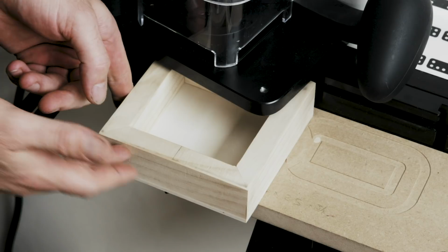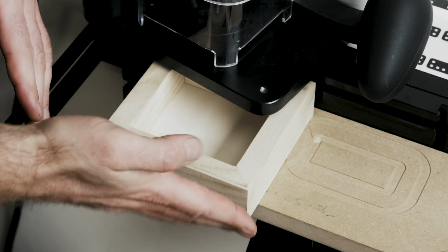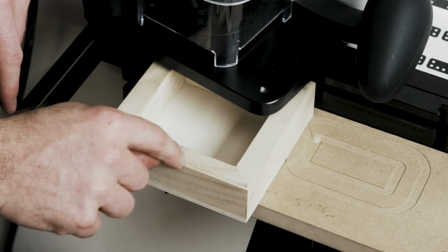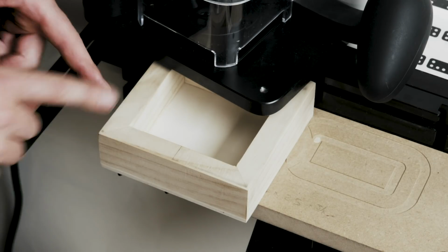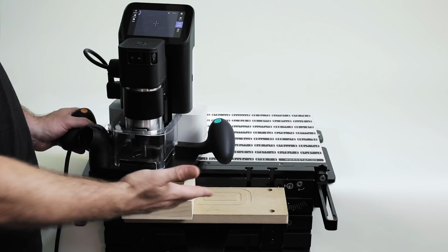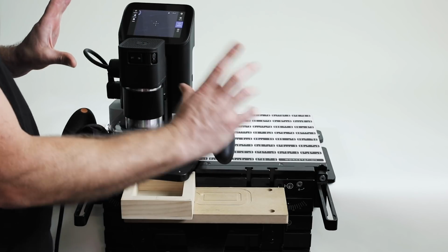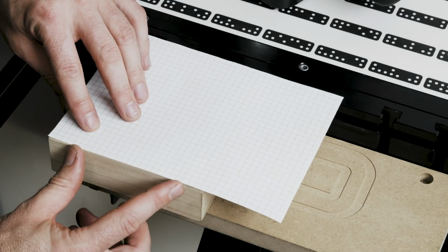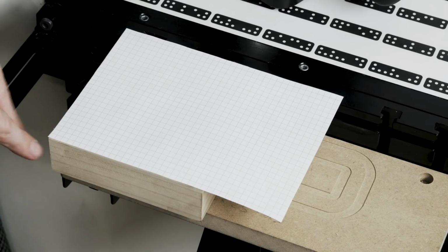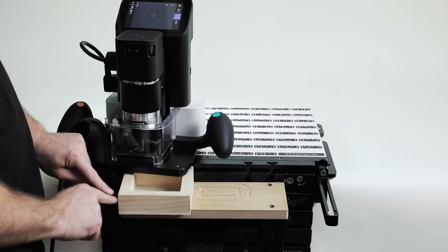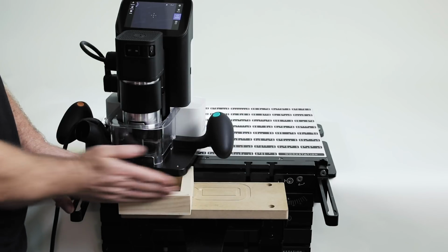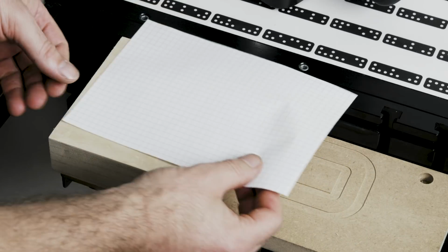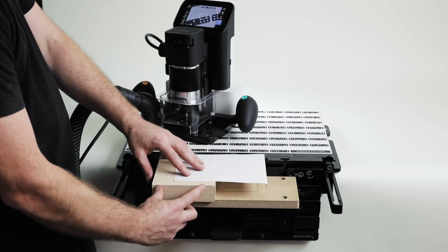The next step is Origin has no idea of where it is relative to the edge of stock. Often we're going to want to place a shape exactly centered on the top or an inch in from these two edges. So the gridding process is taking effectively a grid, think of gridding paper, and aligning it to two edges of this. One edge will be the x-axis, one edge will be the y-axis. We're trying to get a 0 point here with x parallel to this edge, running right along that edge, and y running along this edge. It's basically just like applying grid paper to the corner of your object.